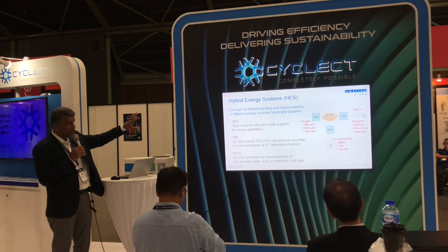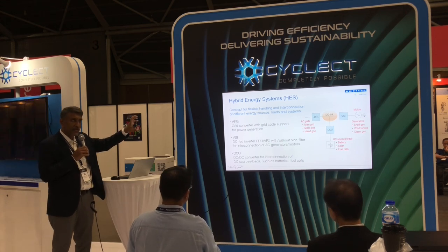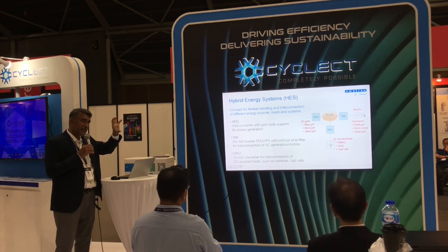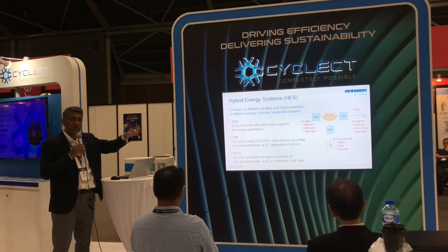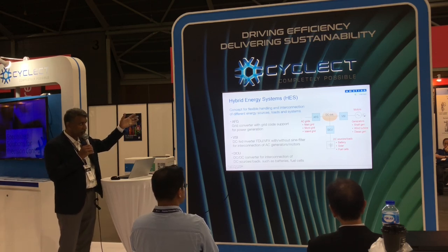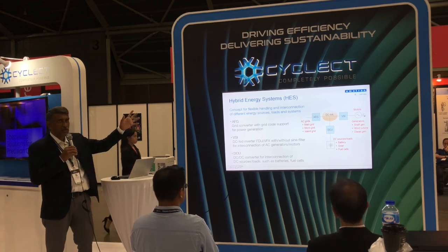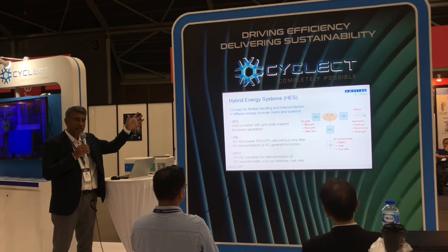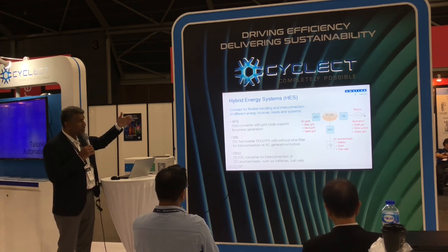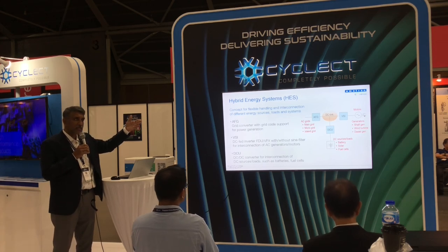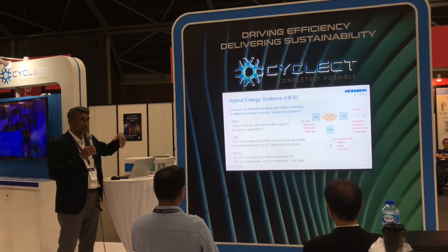So, one product that you see here is called the AFG. The AFG is a front-end device which is connected to the grid, which basically converts your AC voltage to a DC voltage, okay, in various forms. You have something called a VSI, which is a conventional inverter, which converts this DC to AC. Now, all of you are quite familiar with inverters because they are used for variable speed drives. Okay? And then you have another device called a DCU, which is a DC to DC converter.